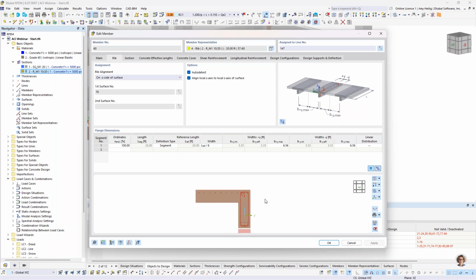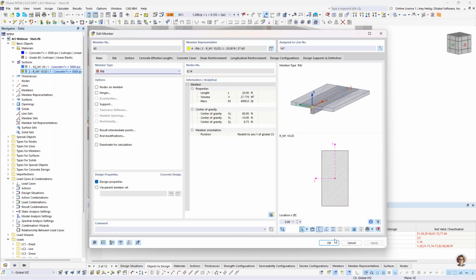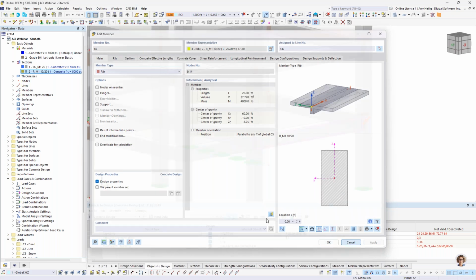So then we further have the ability to integrate the internal forces loads from the slab element itself from the static analysis, and then we can design it as a T-beam within the concrete design add-on. Now, for this rib element, we're at the edge of a slab, so we only have effective width defined here over on the left-hand side.